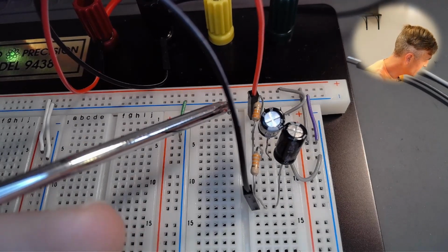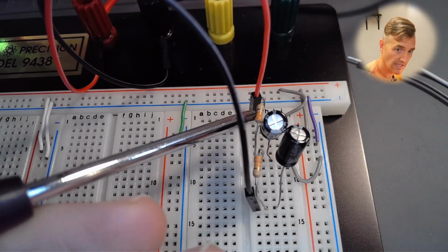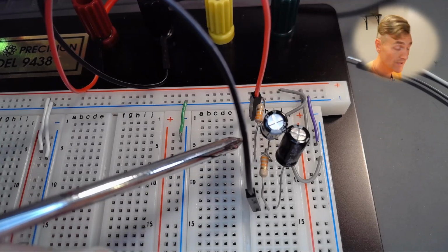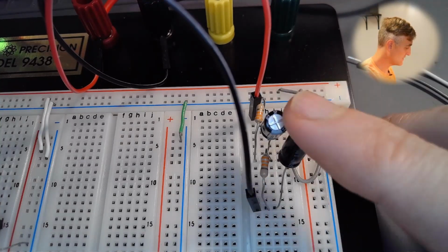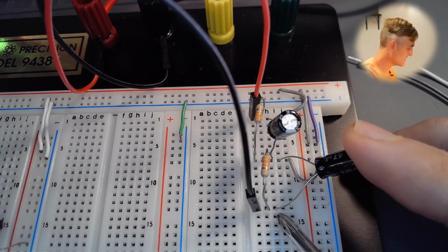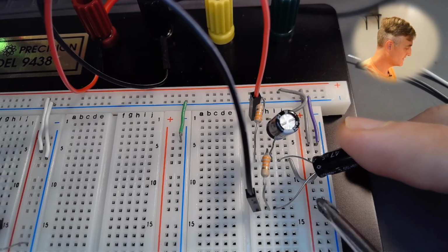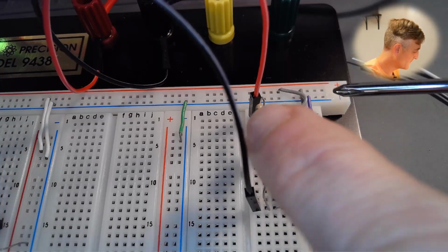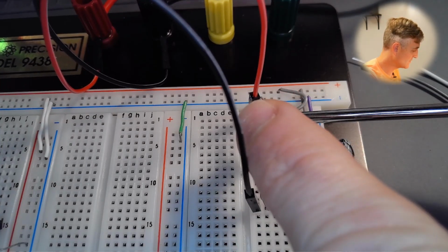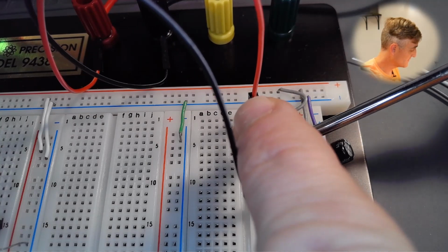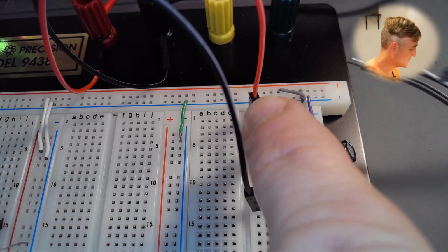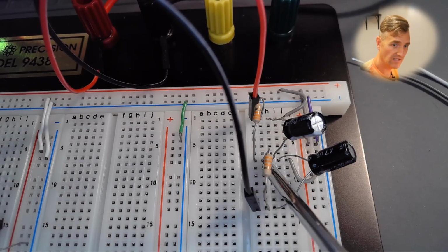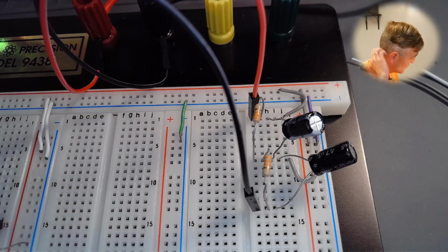I have my 33 kilo ohm resistor right here. That's the top one. And then I have the bottom 33 kilo ohm resistor. Then I have my two capacitors wired so that the positive side goes to the bottom negative lead and the ground side of the capacitor goes to my virtual ground. Same for up here. Capacitor positive lead goes to the positive voltage and the negative, or the ground side of the capacitor, goes to the virtual ground. And this center line right through here, that is my new virtual ground on my board.